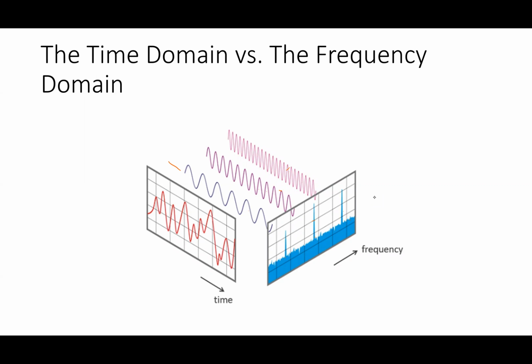So here I have what would be a real signal. In this particular case, this signal can be decomposed into, as I've shown here, basically 3 different sine waves that have frequencies that are harmonically related to each other. And if I look at the frequency domain, these are basically impulses. So in this case, I've got something at f naught or omega naught, right? And then this one, let's say, is 2f naught, and this one is 3f naught.